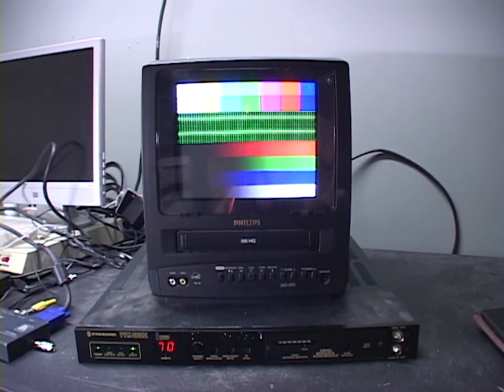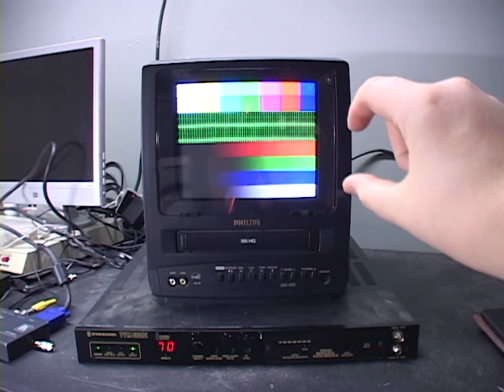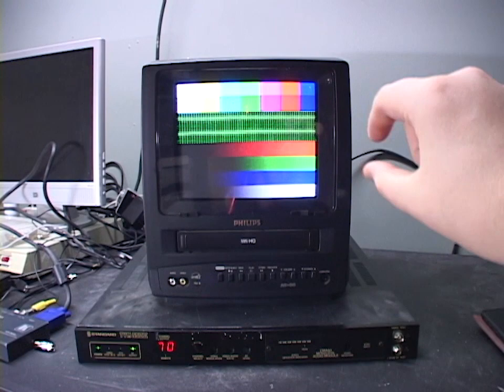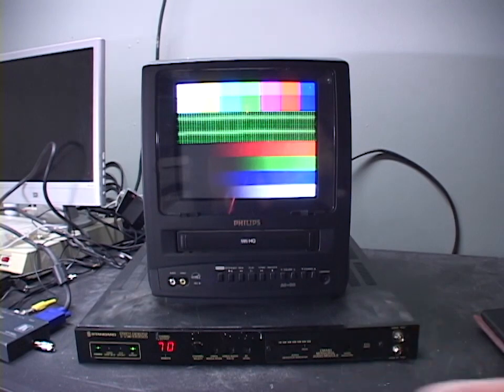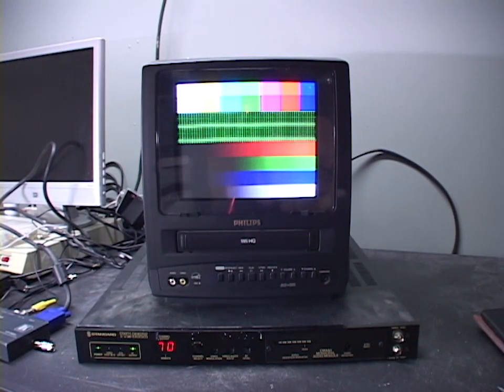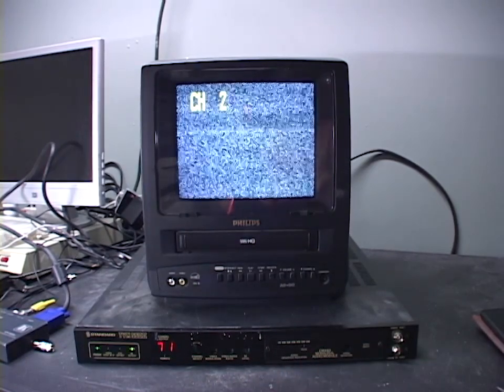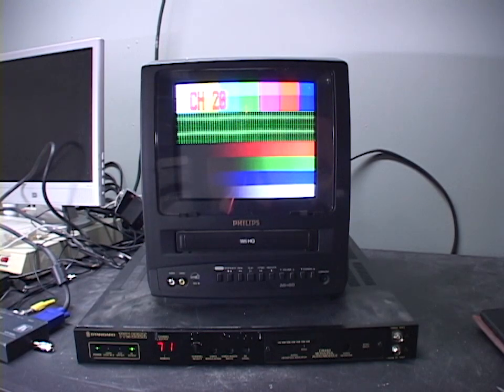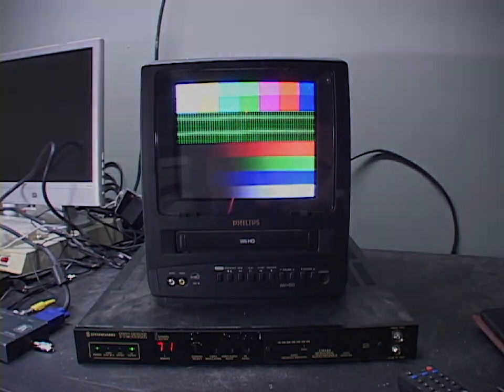And this doesn't have to go for modern TVs either. A vintage TV with the old-fashioned knob dial tuner, well, I think most of them have fine tuning on the inside knob as well, and you can also tune those into these cable channels by going to the appropriate UHF frequency. For cable 70, it's 19. For cable 71, I think it's 20. Let me just check that. Yeah. And so a lot of cable channels somewhat correspond to certain UHF channels.